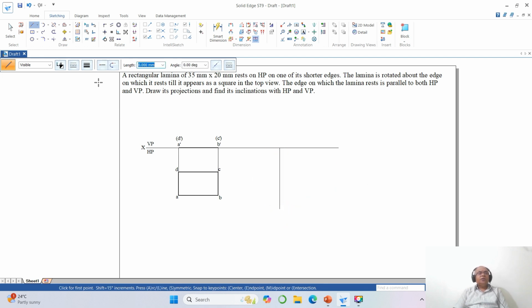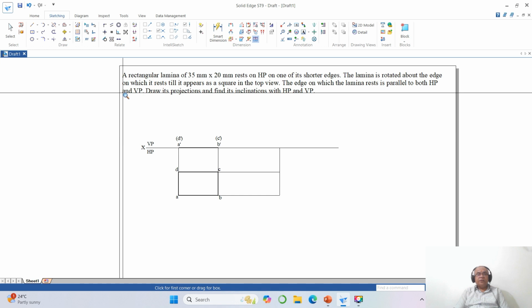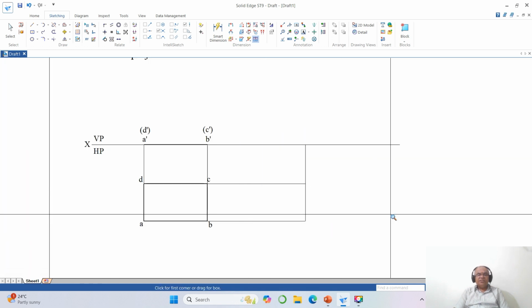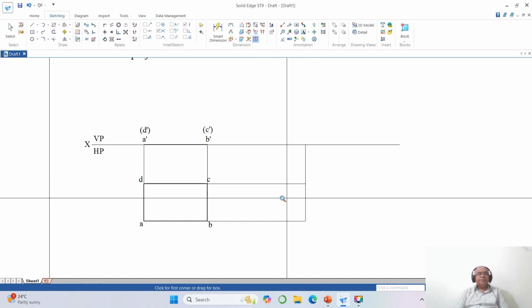Okay, so remove point on element, I don't want to keep it. Then from there I will go to line, take the intersection point of these two and draw a vertical line, horizontal line. Similarly, from the intersection of these two, you draw one more vertical line, horizontal line. Then go to trim between this and this and this. So what is the side now? The side that we are going to get is BC. It is a side of 20 mm.